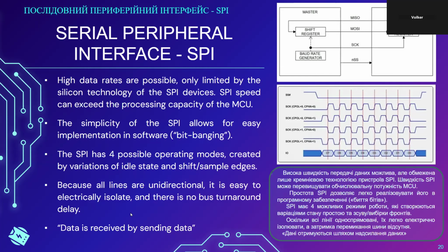Imagine that you need to measure a very high voltage. So for example, 220 volts. And you want to use an A to D converter for this. And you cannot connect the AC mains power, for example, the 220 volts, directly, because of regulations, directly to your main microcontroller.